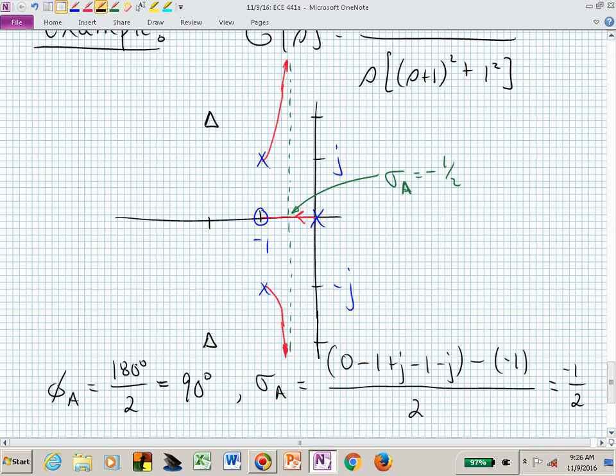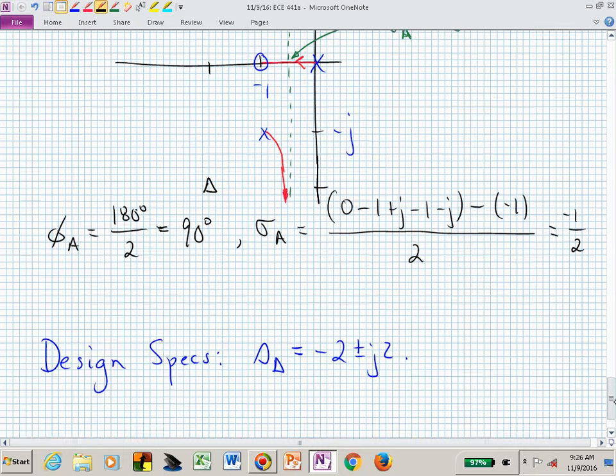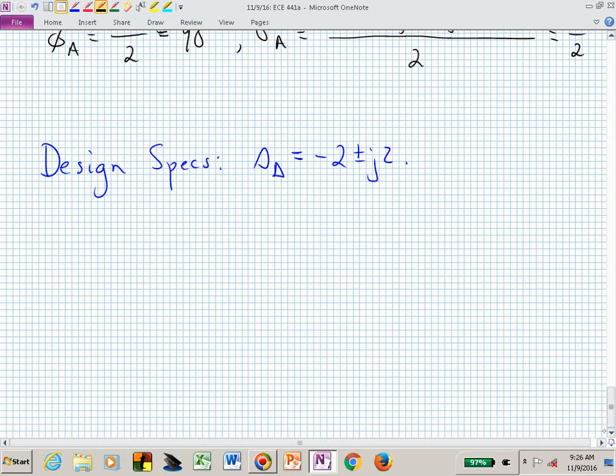If we just had a gain in our controller, we would achieve what we've sketched with the red curve. Can we get to those triangles with just the gain? No. Isn't that obvious now from the root locus sketch, a very quick root locus? We are not going to go through those triangles. That said, our controller needs to dramatically change or drastically change the root locus, the original root locus.